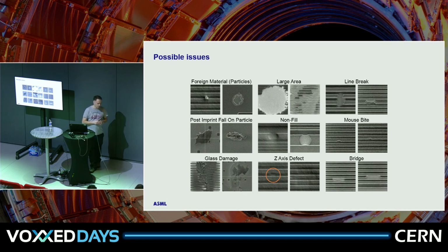And it's not always a really big problem. Depending on the chip manufacturer and the design of the chip, they can actually build in a redundancy. For example, if you have memory chips of 32 gigabytes, and we detect that there is a fault in one part, we might disable that part and sell it, or our customer sells it as a 16 gigabyte chip. Same for processors.